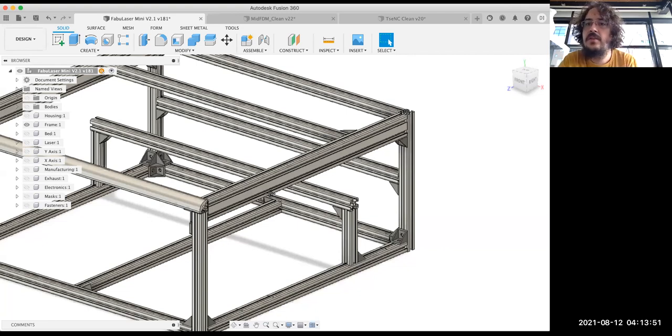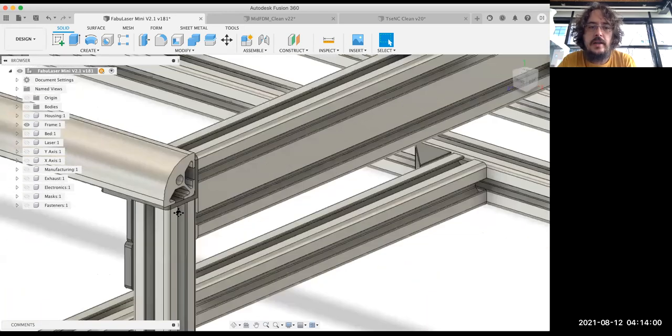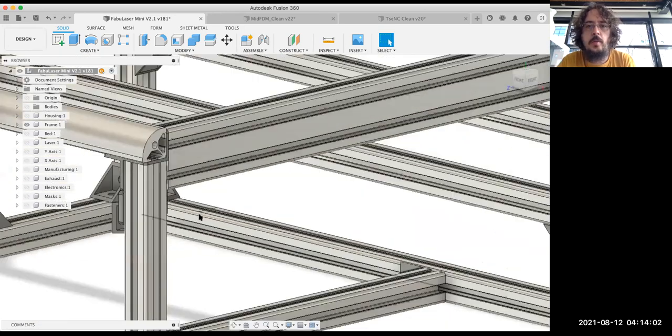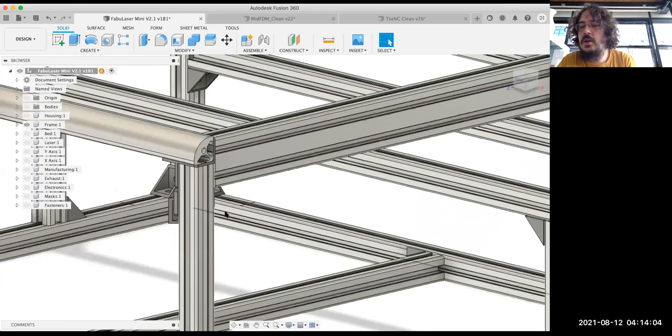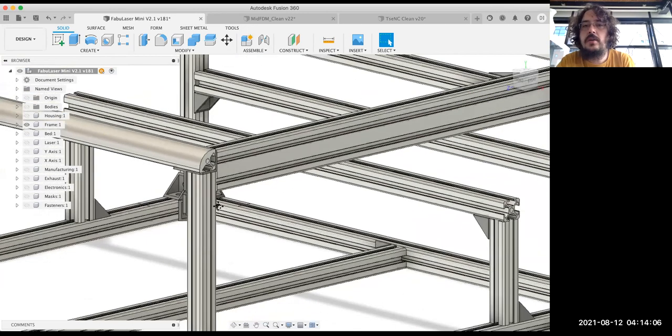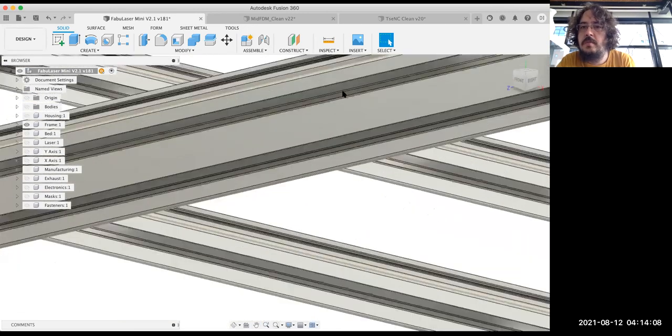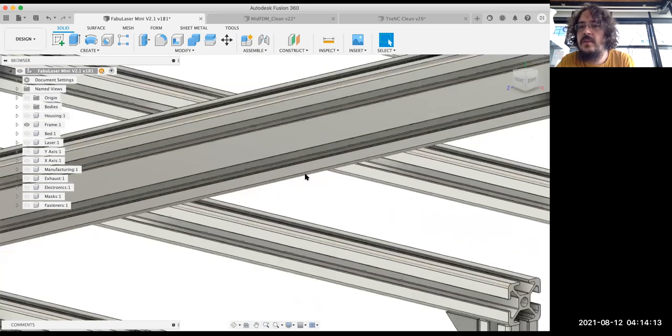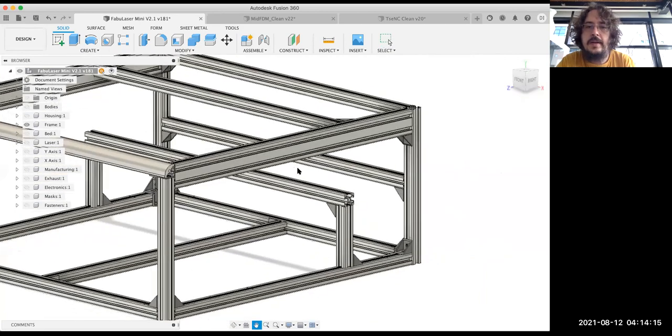You know, they cut it with very high precision, and they come out of the factory rather straight. So if you also use the surfaces of the profiles and some aluminum brackets to square the profile, your frame is going to be square. And on top of that, you can screw on any point of these profiles along the rail. So you just put T-nuts and they become surfaces available to screw anything on them, you know?